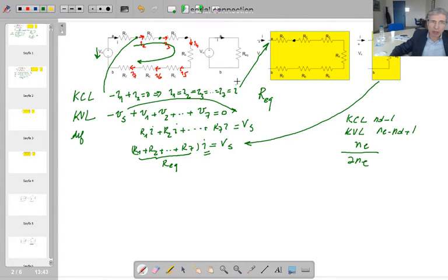So if there are 2 resistors connected in serial, this number is going to be reduced by 1. For each serially connected resistor pair within the circuit, you're going to reduce the number of equations by 1. So the total number of equations that you're going to solve will be reduced. Therefore, it helps the analysis. So this equivalent concept usage for resistors helps to do analysis in a better way. So that is one of the advantages.